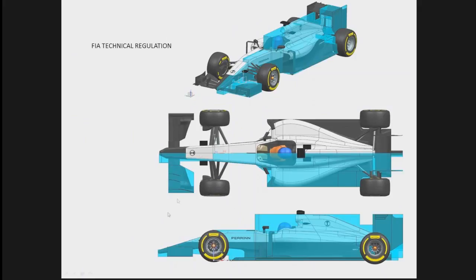We need to have a low nose now. If you raise the nose, what you tend to do is you actually decrease the front downforce, purely because there's no such pressure pushing on the nose, obviously. And yes, you allow more flow in the center of the car under the chassis, which has some benefits for the diffuser. So it's a better quality of air going to the back of the car, but you've lost front downforce as well. So you have to see if overall it's better. I think a high nose was better overall, and if people could choose, they would probably want to go back to a higher nose. But the low nose works as well.